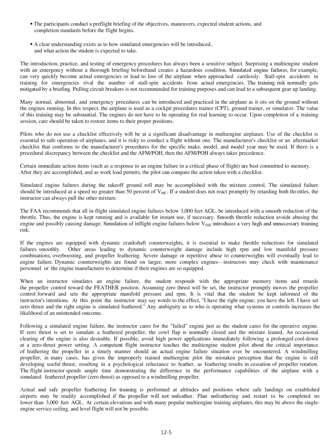Following a simulated engine failure, the instructor cares for the failed engine just as the student cares for the operative engine. If zero thrust is set to simulate a feathered propeller, the cowl flap is normally closed and the mixture leaned. An occasional clearing of the engine is also desirable. If possible, avoid high power applications immediately following a prolonged cool down at a zero thrust power setting.